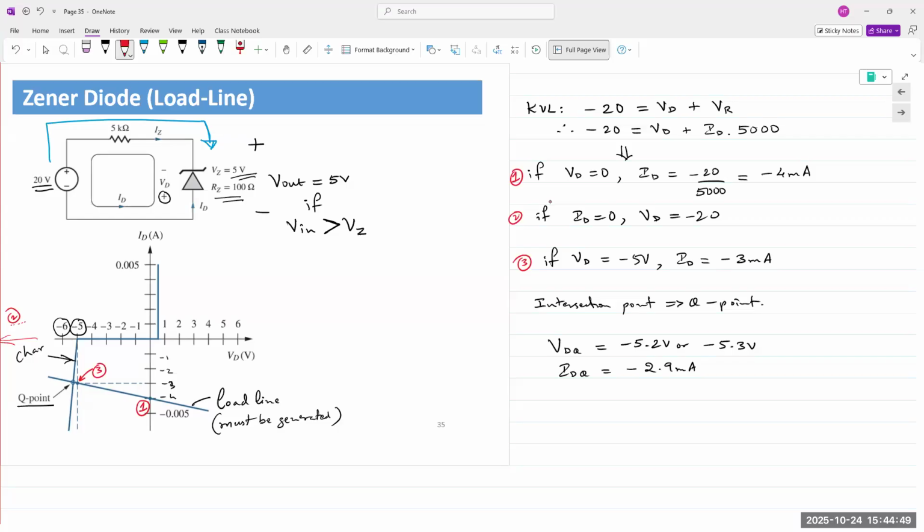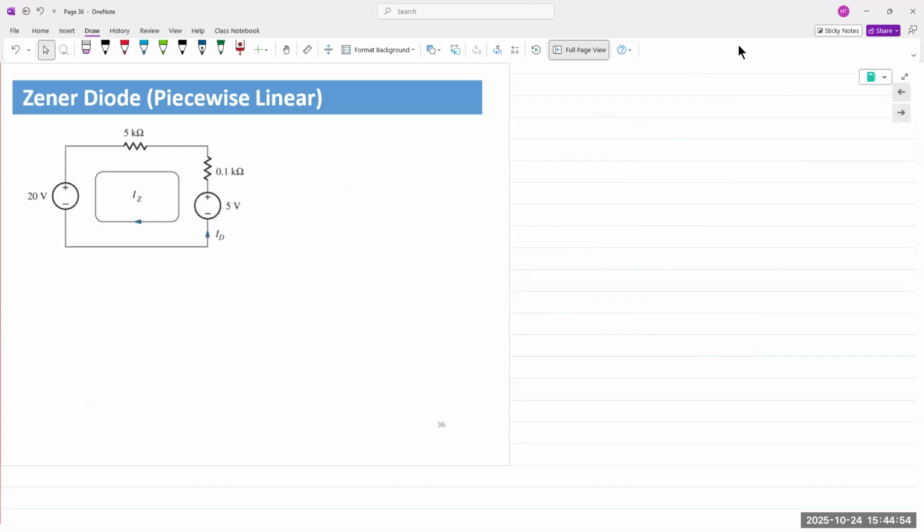All right, we've got 15 minutes left. So, piecewise linear analysis. Anyone hear of this technique before? Piecewise linear, kind of. Okay. The piecewise linear technique simply assumes, well, not assumes, but we have nonlinear devices, right? But, and this is again an important concept that we'll encounter later, if we look at a very small portion of the characteristic or a very small portion of the device over its operating range, we can treat it as linear just for that portion.